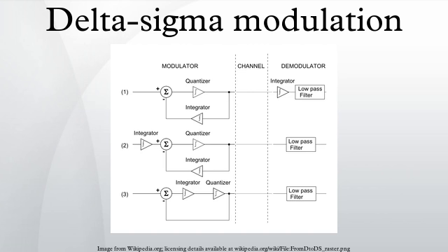The circuit itself is relatively inexpensive. The digital circuit is small, and the MOSFETs used for the power amplification are simple. This is in contrast to a multi-bit DAC, which can have very stringent design conditions to precisely represent digital values with a large number of bits. The use of a delta-sigma modulator in the digital-to-analog conversion has enabled a cost-effective, low-power, and high-performance solution.